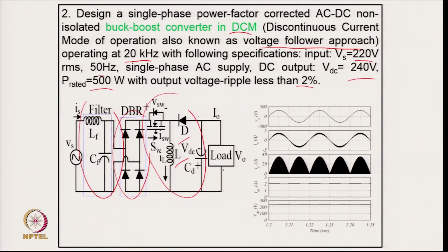After designing the components, with those components and with power control, a model is developed, from which you have a supply voltage and supply current. The supply current is in phase with the supply voltage and almost close to sinusoidal, and you can see this inductor current is discontinuous, as this inductor is designed in discontinuous conduction mode, and this is typically the load current and output voltage. You can see clearly here that it is quite good quality output.